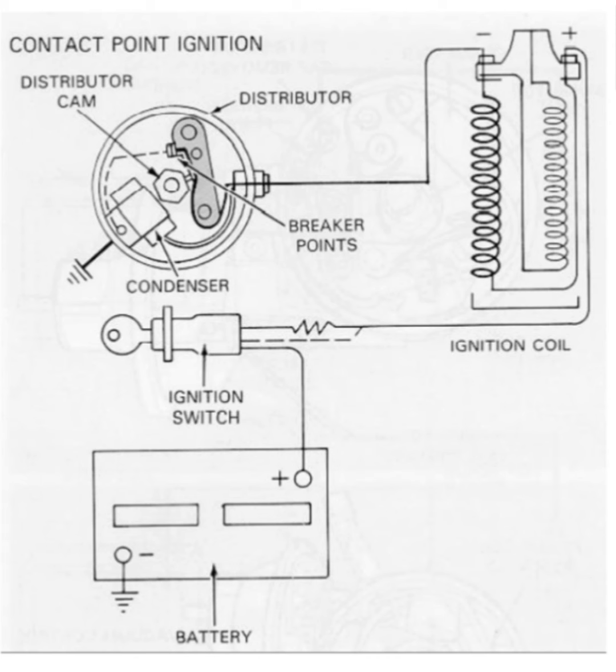The lines of flux in the magnetic field cut through the secondary windings of the ignition coil, creating a high voltage, high enough to jump the gaps between the rotor and the distributor cap terminals and the electrodes at the base of the spark plug. Assuming that the engine is properly timed, the spark reaches the air-fuel mixture in the cylinder and combustion begins.